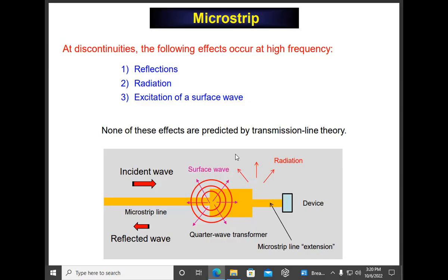Normally, in the power world, power engineers use transformers to change from one voltage level to another, right? You want to step up the voltage coming out of the power plant and send a really high voltage down the high distribution lines, because high voltage means low current, and it's current that corresponds to loss. You want to keep the current as low as possible, and therefore the voltage as high as possible. And then, of course, you have other transformers like the substations that step it down before it goes into a factory or eventually into your home. So that's the main use of a transformer in the power world.